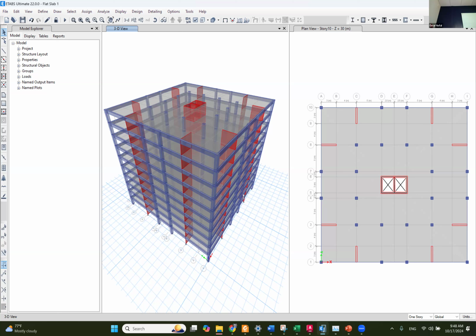There's a way, it's called DXF file, and we create the mesh and we create everything. This way can work for SAP 2000 and ETABS. We do the meshing and everything is ready to be an element. You can create your entire structure and import it to SAP 2000 and just put the loads and run the analysis. So that's a way, but it takes some time to finish it on SAP 2000. The DXF approach is that you create the elements, the beams, the columns, the slabs, the meshes and everything, and you just assign materials, sections and loads and run the analysis.